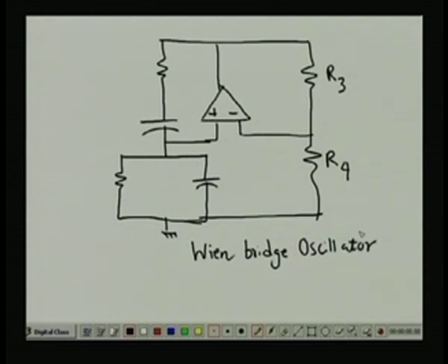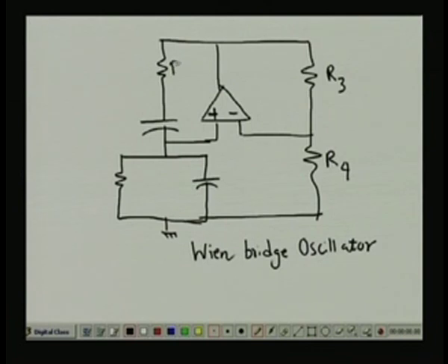These Wien bridge oscillators. Now, see that always we will try to make the gain of this amplifier very high to oscillate. We will always make this gain of the amplifier quite high. Now, there are some resistances, suppose this is R, this should be R, if it is C, this should also be C. There is no doubt about that, and the frequency of oscillations omega naught will be equal to 1 by RC, right. Now, there are two resistances you see, R3 and R4.